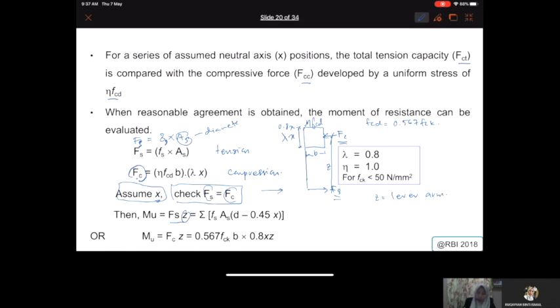Because we want to multiply the moment, you have the tension in this direction and your compression in this direction, one on this side and one on this side. So you have it calculated. This must be the total, because you might have not only one layer of steel, you could have multiple layers of steel.